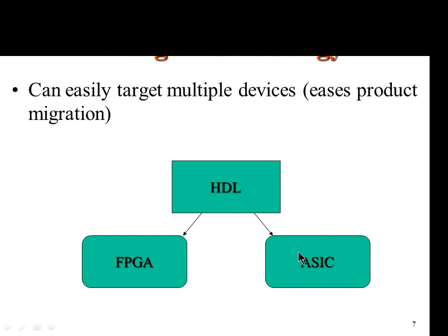And if you use any such block from those libraries, your design is tied to that ASIC vendor. Or if you use any block from the Xilinx FPGA library or Intel FPGA library, your Verilog is tied to that particular FPGA device. So wherever possible, don't do that. In case it is required, you will end up doing that. But then you have to know that the Verilog is not independent. There is a dependency on this technology family.